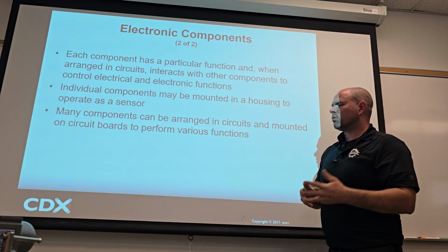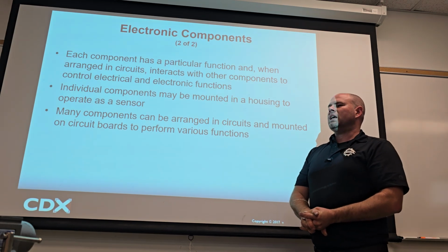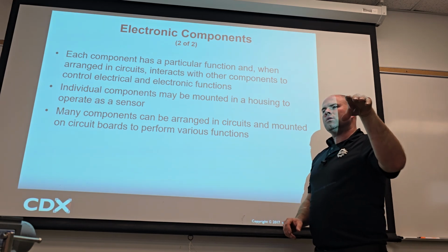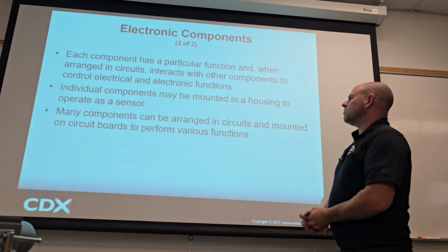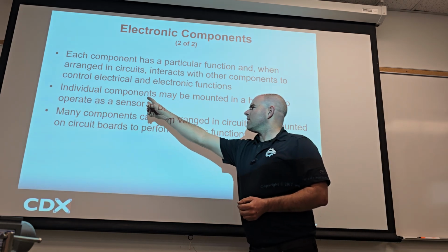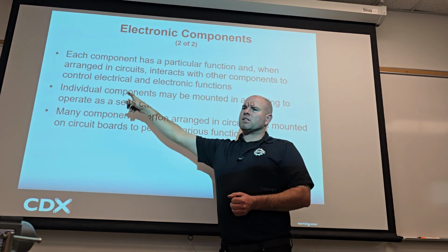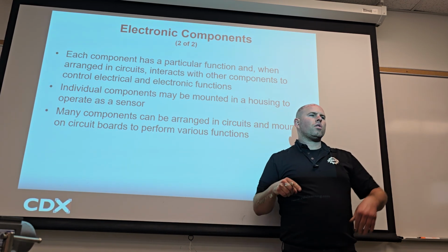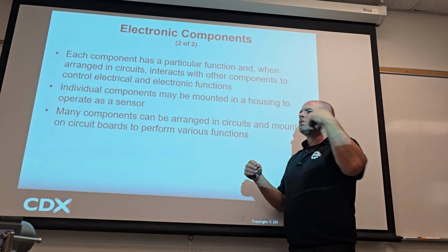The good news for us is we don't necessarily always need to know exactly what's wrong. We just need to know that the problem's inside the ECU or inside the sensor, or it's the wiring. Cool. So for example, all these individual components are probably going to be mounted in a housing and operate as a sensor. So as a technician, you'd need to be familiar with, oh, that needs a crankshaft position sensor,